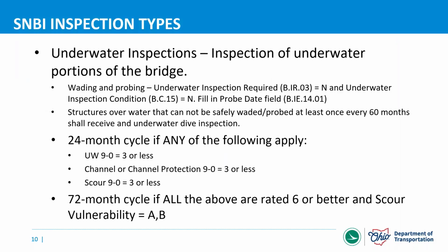dive inspection cycle. And then for 72 months, if all the above are rated 6 or better and your scour vulnerability is stable, meaning an A or B rating there for scour vulnerability, you could potentially have a 72-month cycle for underwater inspection. So Ohio will have a lot more bridges that are applicable for a 72-month cycle than they will for a 24-month cycle.